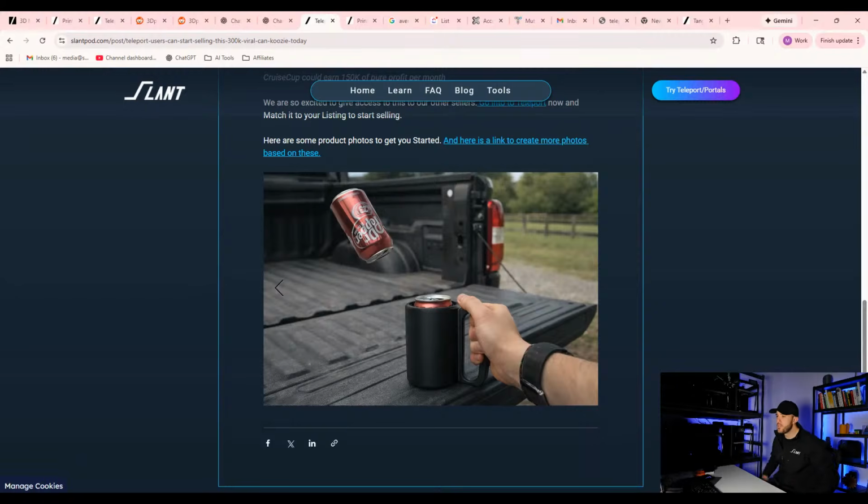Farouk, is it possible to use PLA for snap joints? Other filaments are not available. Yeah, Farouk, you can totally do that. Make sure you design them appropriately. If you're doing snap joints, make sure they're in the plane of the layers. That way they bend along the layers, and that way you can use PLA just fine. This is a PLA part right here. It is also matte PLA, which is super brittle, but it will continue to shoot cans for a long time and have that flexibility inside of there.